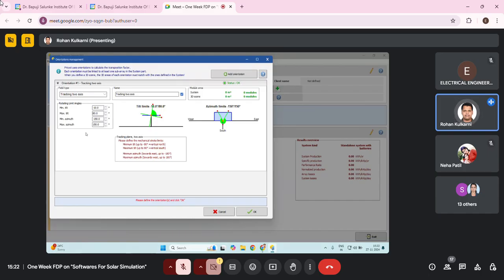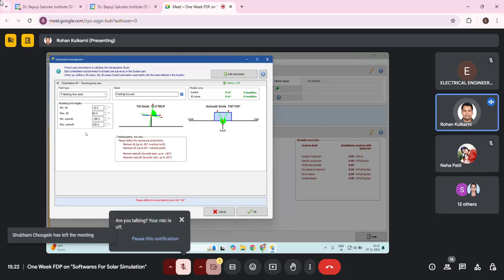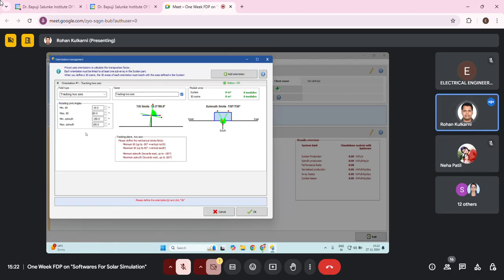Once we install the solar plant, the only maintenance is the cleaning of the solar panels. But once you add the tracking system, it will add some maintenance, like motor maintenance, actuator maintenance, and all. Second thing, what is the known value of how much we get using tracking? As per the published data, we can get a maximum of 39% extra from the tracking system.